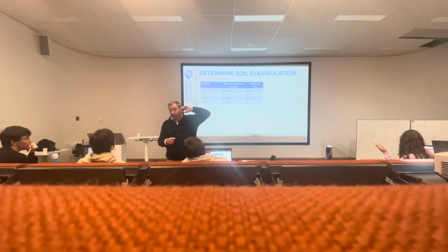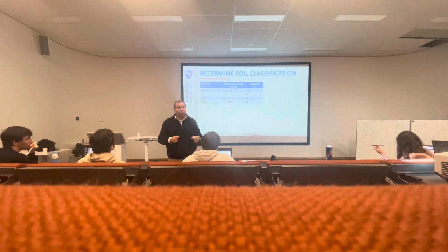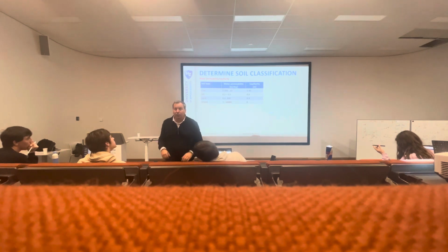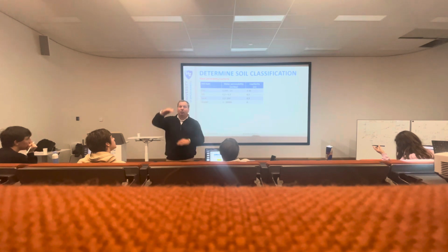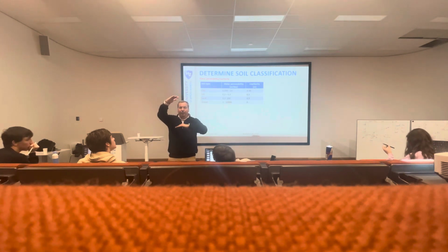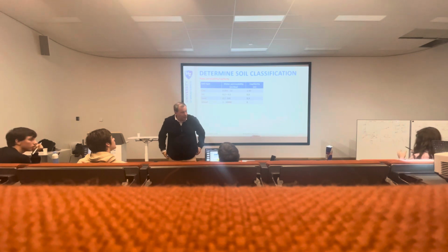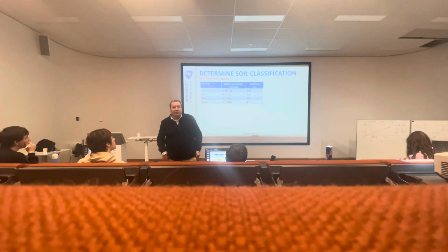But you have to be aware also, when you are closer to the sea, you can also get salt water upwards. And that's something we don't like, salt water, because then nothing can grow there anymore. So we have to make sure that rainwater, which is sweet water, is always floating on top of the salt water that is being pushed from the sea. So we can't just drain all the water out, because then the sea just brings salt water in.